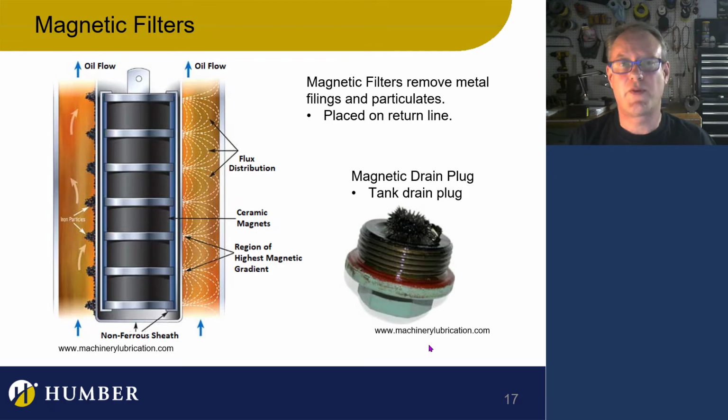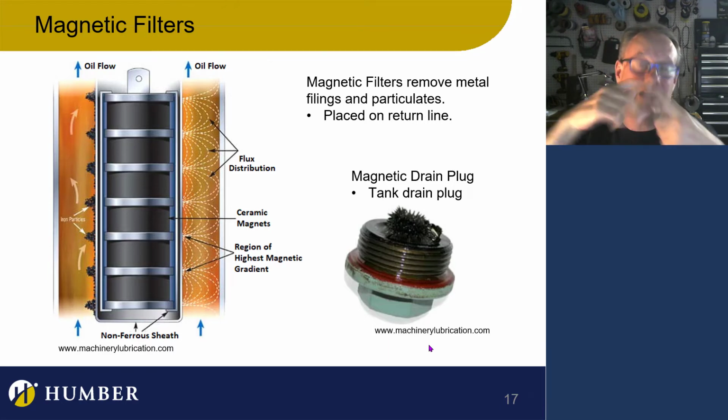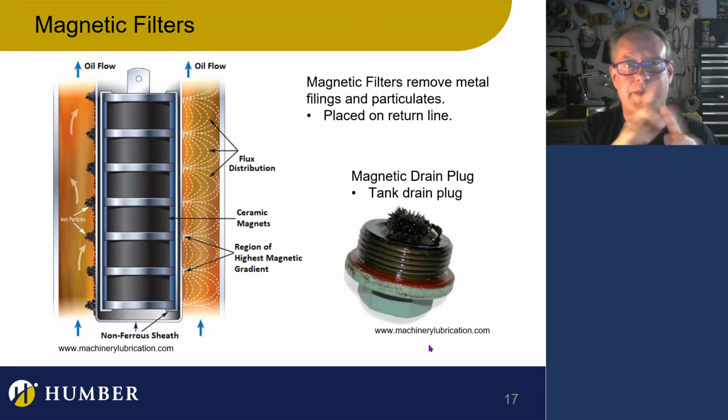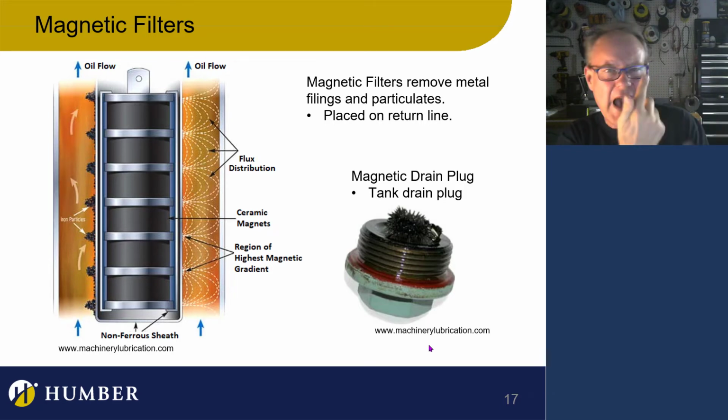Actually, get this, the reason that those particulates end up in the hydraulic fluid with the actuators moving and the gears moving and all the rest of it is because there are particulates in the fluid. So those tiny little particulates get into the hydraulic system, they get stuck in between the gears, they get into the bearings of the gears for the motors, they get into the seals of the cylinders. When they're going through the valve, they tap, tap, tap under high pressure and flow. Those little particulates are smacking into the metal and they're tearing little pieces of metal off.